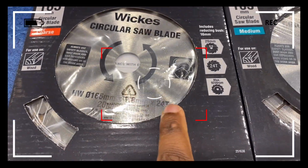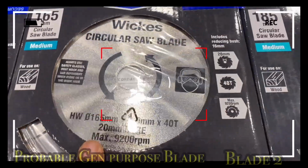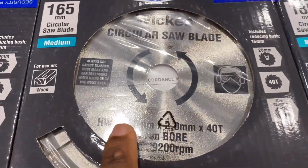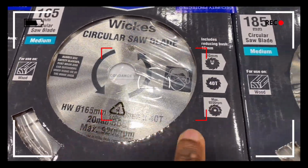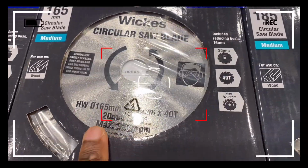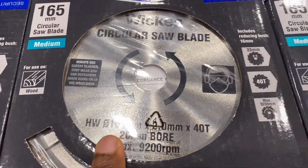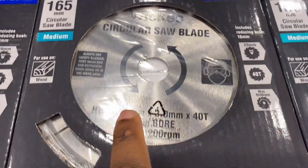The next blade's rim size is 165mm or 6.5 inches. It's got a 20mm bore, 9200 RPM, a 2mm kerf and 40 teeth. It's got more teeth, but it is at the threshold for ripping, so it can be used for medium ripping and cross-cutting.